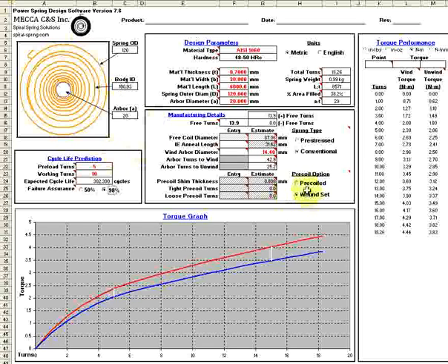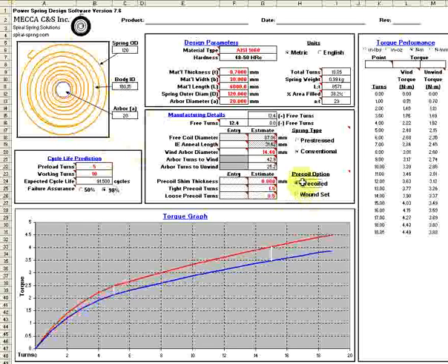By selecting a pre-coiled spring, the winding method is changed, retaining some of the material stresses and reducing the dead turns. In this design, it seems to be the right decision. Further enhancements of this design achieve the torque, turns, and cycles required.